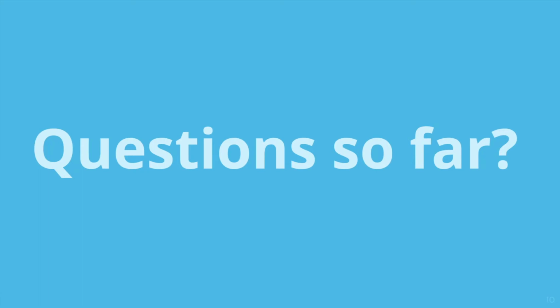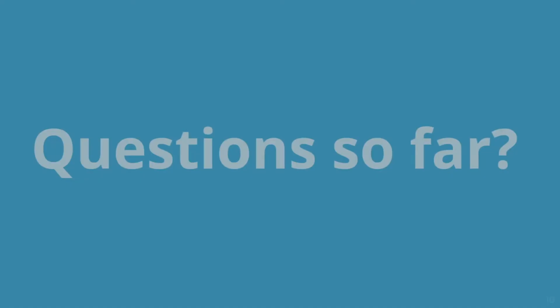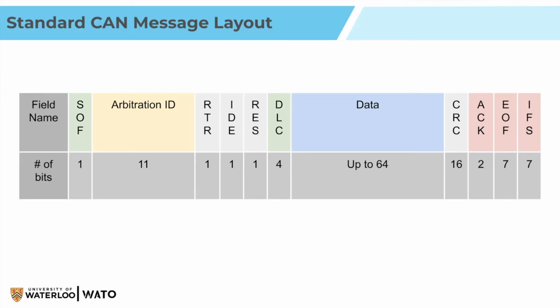I see. Wait, on a CAN network, there is no concept of node IDs, as far as I understand. There's no way to specify the destination. Like you said, when we want to transmit the message to multiple clients, we need to do them sequentially. But I don't think there's a way to identify the recipient.